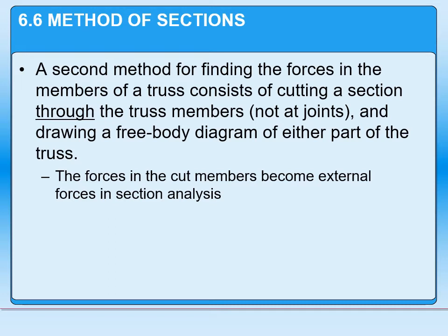All right. In the sections itself, the forces from the cut members act like external forces. They act like something is pushing or pulling on it. If the member was going to be in tension, it would be pulling on the part. If the member was going to be in compression, it's going to push on the part.